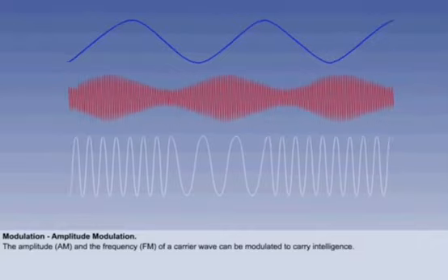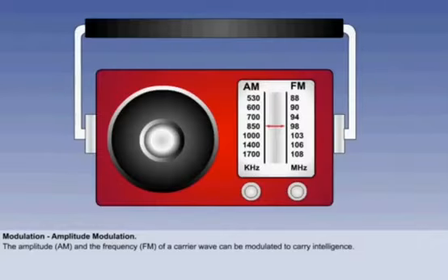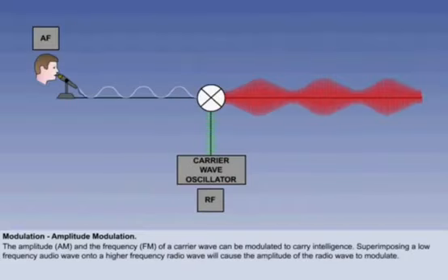You will be familiar with the term AM radio. This means amplitude modulated radio and refers to the medium wave broadcast band 300 to 3000 kHz. If an electromagnetic wave in the radio frequency bands is mixed with a lower frequency wave, such as an audio frequency, the amplitude of the wave will modify the amplitude of the radio frequency.